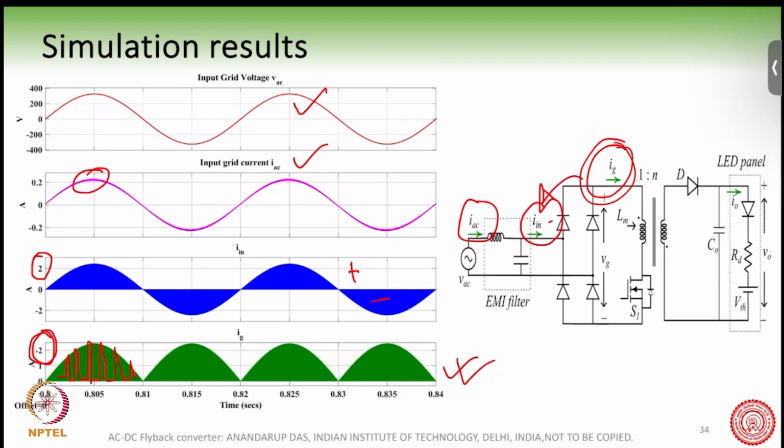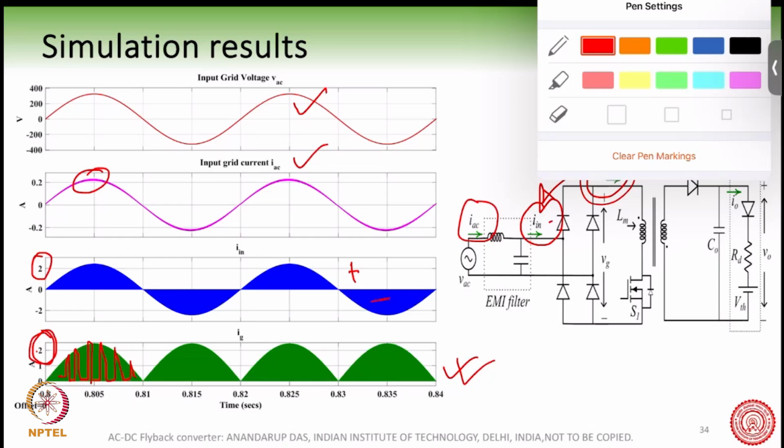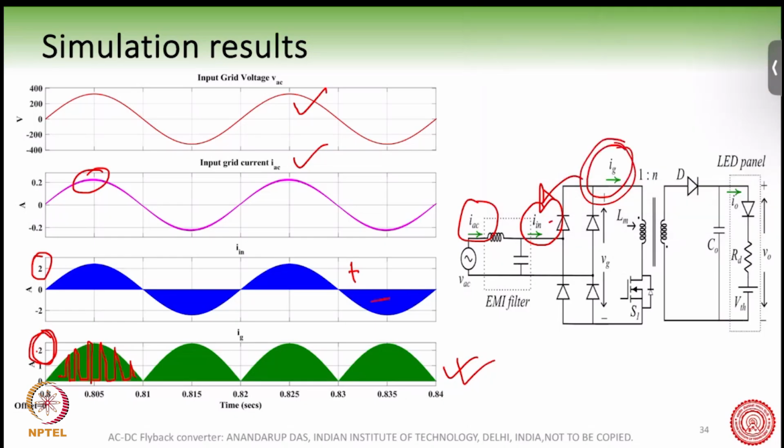Okay, why is it so? This is happening because the average value of the current here is very small. The average is somewhere here. And the peakiness, you can understand the peakiness, the D1 factor. This is the peakiness, but this is the average. So the average value here is like 0.2, or 0.21. This is the peak average value, whereas the peak current here is touching 2 point something, right? So yeah, this is important to note.